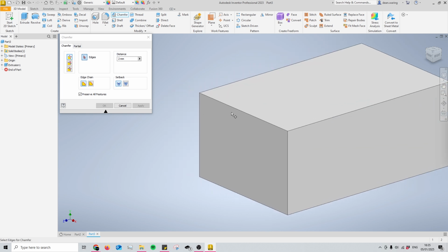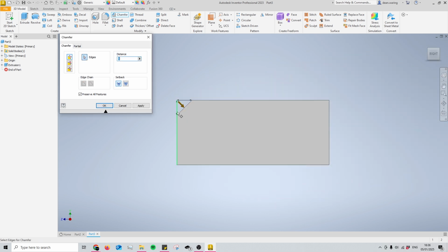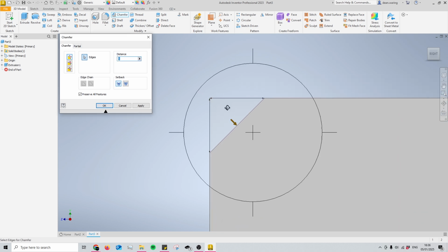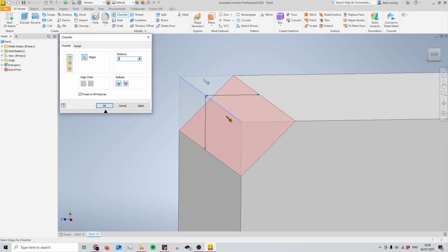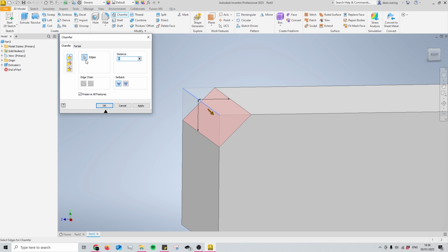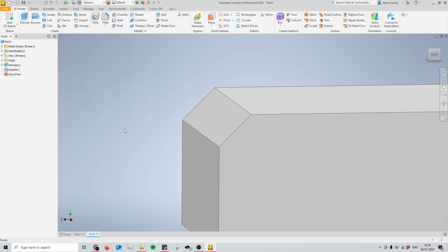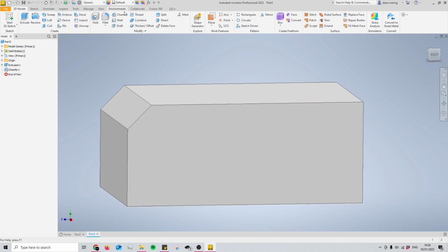So to begin with, the top one is an equidistant chamfer, meaning that whatever number that you put into this input field here will determine where the chamfer starts and finishes. This type of chamfer will always produce a 45-degree angle. So just to clear up how this works, this is the edge that we've selected, this blue line, and you see to the right hand side the chamfer will start 5mm from the edge, and then the same goes for beneath it as well. All you've got to do is select the arrow inside the menu and then click on the edge that you'd like the chamfer to be applied to and press OK. So that is the first basic chamfer.